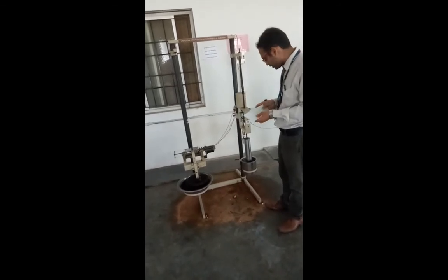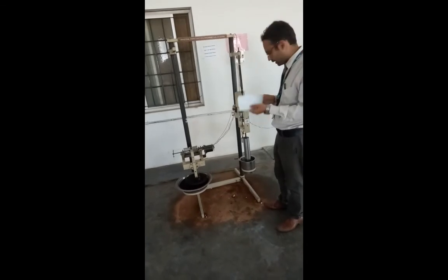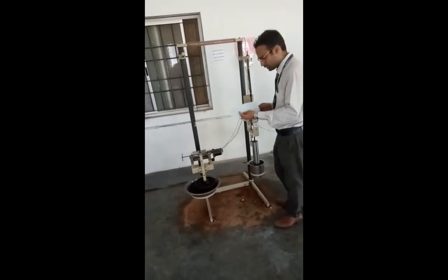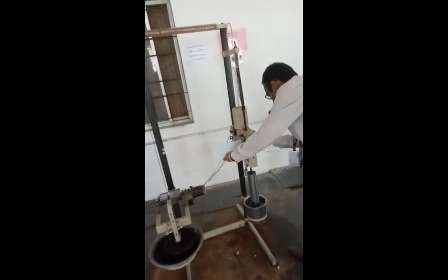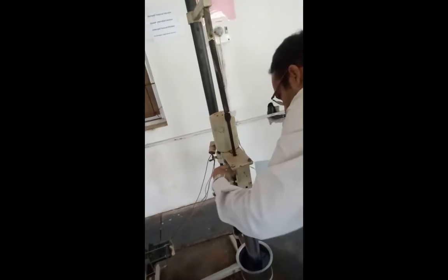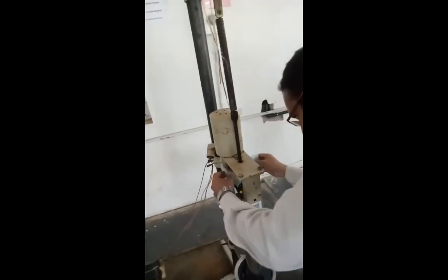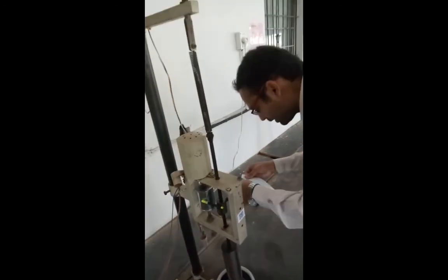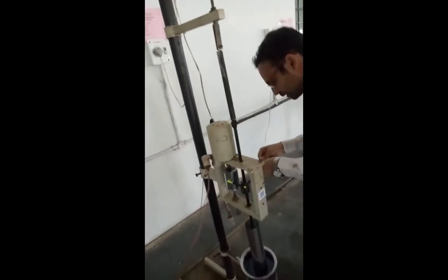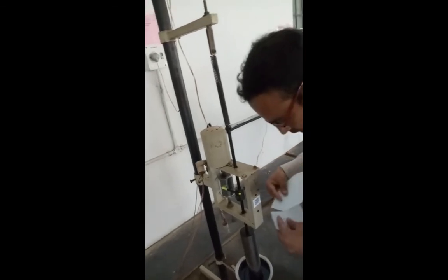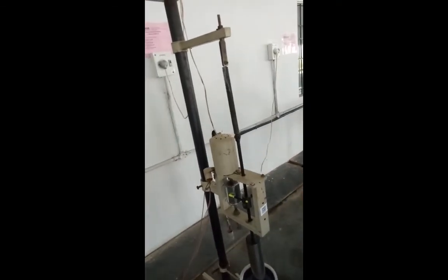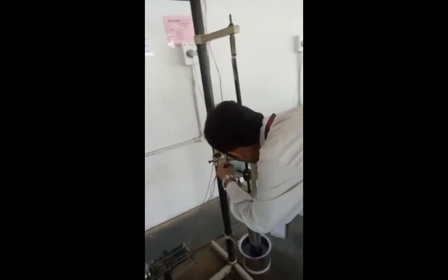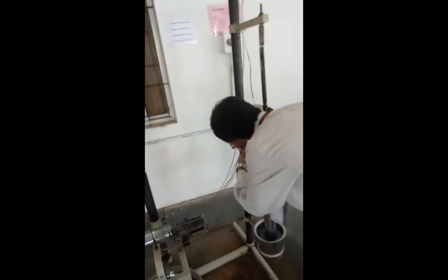Now I am going to tell you the procedure of this third experiment. Take the graph sheet, and follow the same procedure as in the torsional vibration experiment. Fix the graph sheet around the drum tightly, without any wrinkle, and remove the extra part. Fix this graph sheet around the drum so that it does not get any wrinkle. That is the main point.